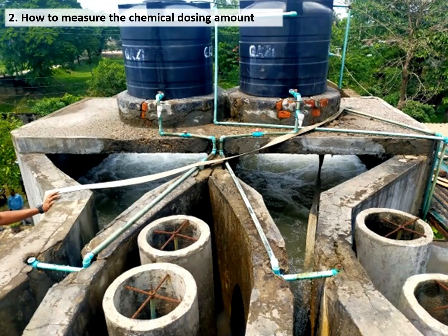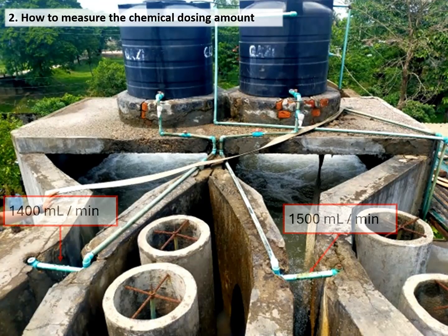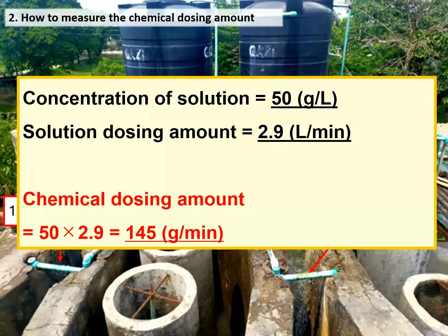Normally, there are some dosing points at the plant, so the amount shall be measured at each point. For example, when 1.4 liters and 1.5 liters of solution were observed from 2 dosing points in 1 minute, it means 2.9 liters of solution are dosed. Considering the concentration of solution, 2.9 liters times 50 grams equals 145 grams of coagulant powder mixed in 1 minute. Now the chemical dosing amount is confirmed.